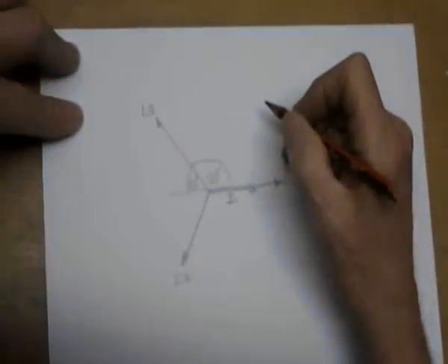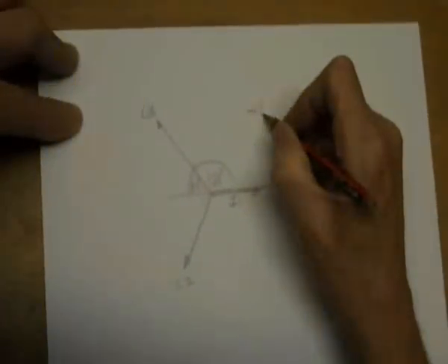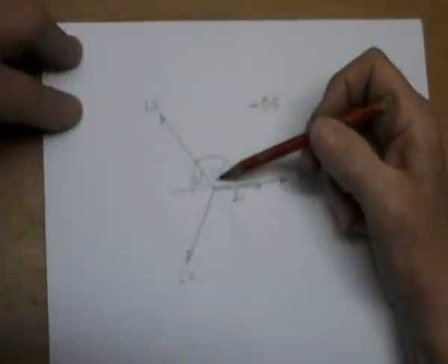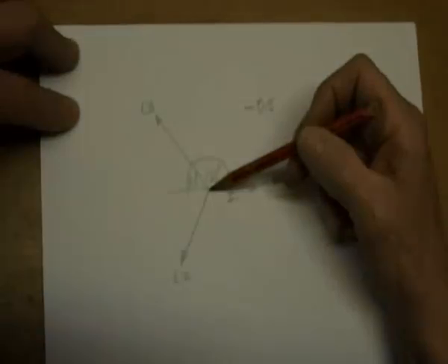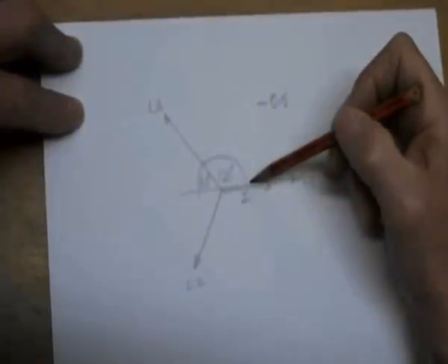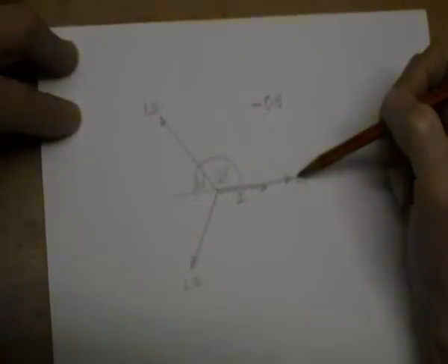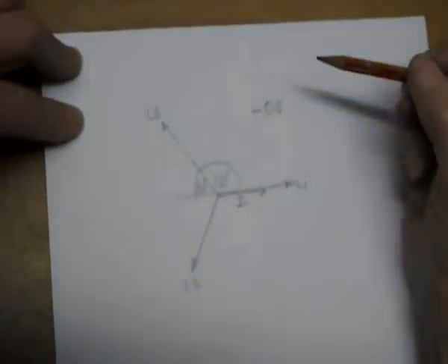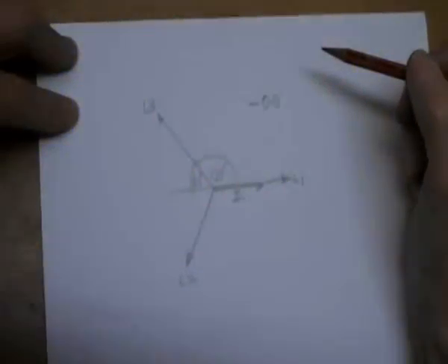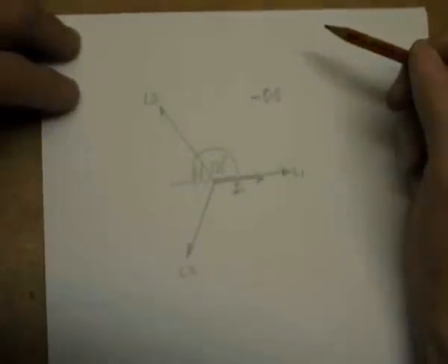The cosine of -60 is -0.5. So it would be recording a power factor of 0.5, when in fact the current is totally in phase with the voltage, and it would lead to the presentation of false information.